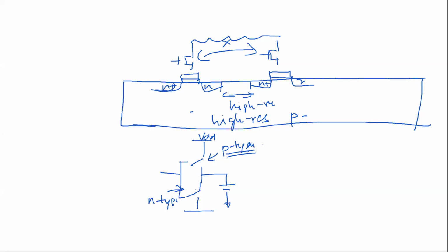Actually, we do now, with the SOI process, silicon on insulator. That's how they do it. They actually put all the devices on glass, literally on glass, so that it's insulated. But the cheaper processes or the older processes are still done on a P-type material. So all the devices, even the PMOSes, are done on a P substrate, where you first make what's called an N-well, then put the PMOS. For the NMOS, you just put it straight on the P substrate.